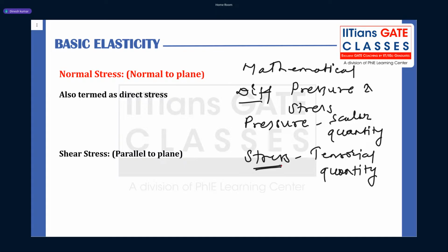Now, guys, this is in general. You should know before starting what is stress. So, generally, guys, stress can be of two types. One is normal stress, okay, and another is shear stress. Normal stress is also known as direct stress, and usually normal stress or direct stress is denoted by sigma. So this sigma is what? Limit delta A tends to 0, delta Pn by delta A.